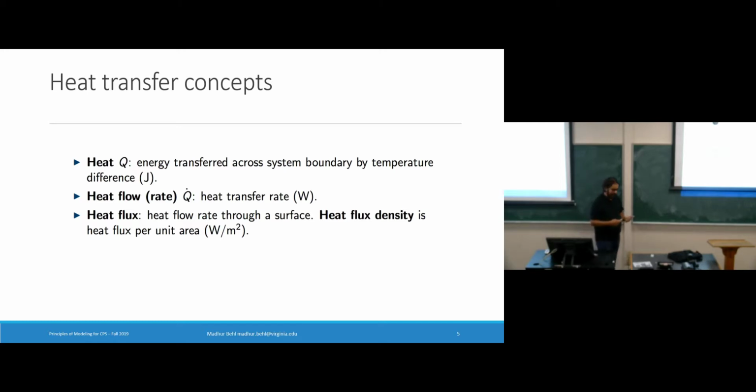And then there's something called heat flux. Flux in general is when you define something per unit area, or you define some flow per unit area to be precise, that becomes flux. So the heat flow rate per meter square of any surface, I can call that quantity flux, and we will often use the solar influx from the sun directly onto a wall, for instance, to predict the temperature of the wall. In that context, you will see this in a bit, but sometimes that solar flux is called irradiance or solar irradiance. So this is well known.